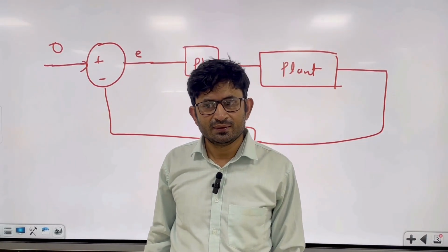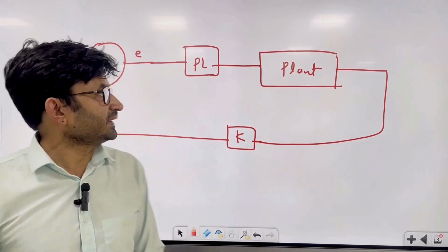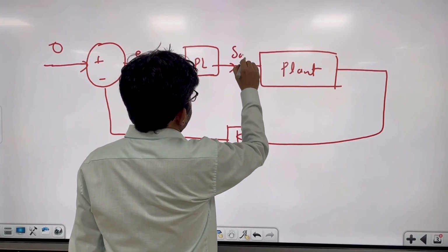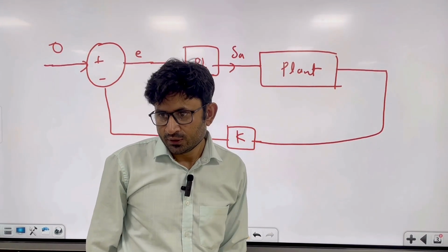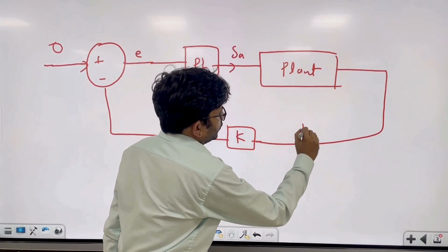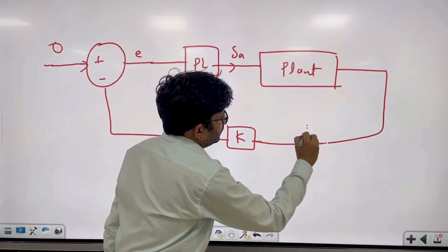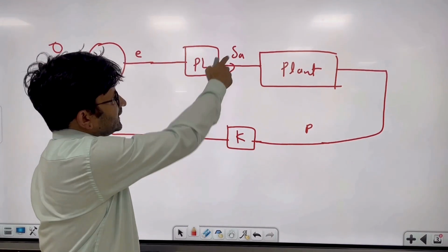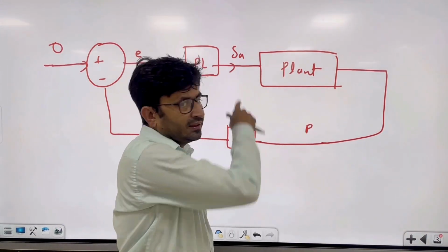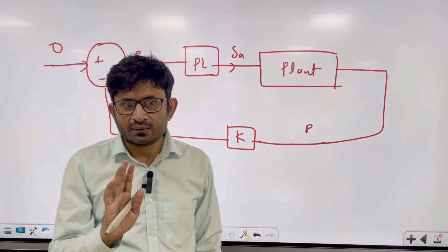That is stabilization. In this roll rate case, this is the aileron input. When you change from P to Q, that can be the elevator, and when you change from P to R, that can be the rudder.